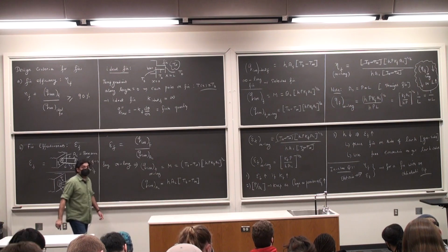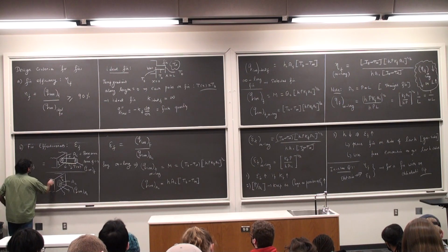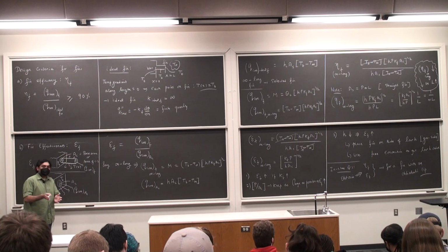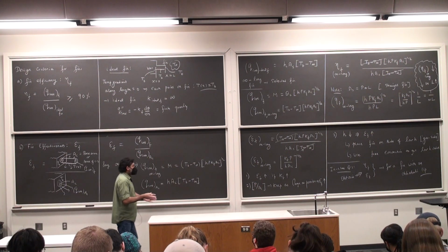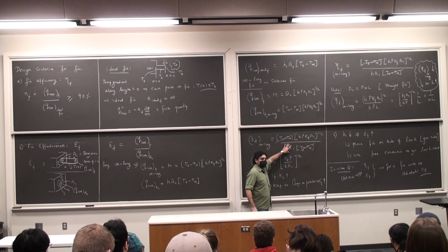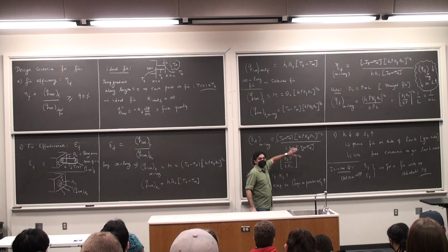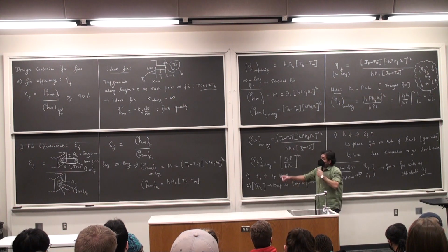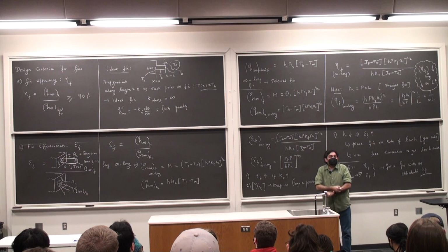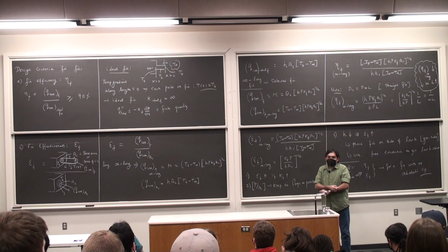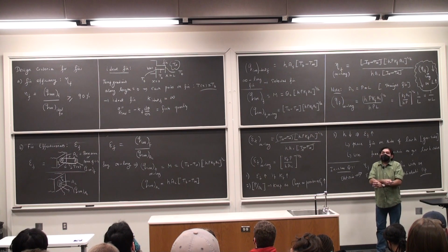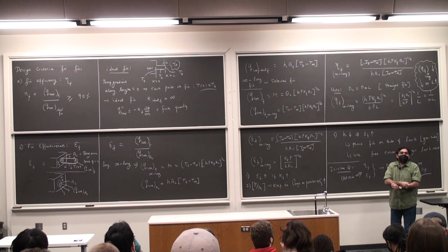Things that do not change: the denominator in the efficiency and effectiveness does not change whichever fin you select. So that's going to be the exact same denominator for the effectiveness for any kind of fin that you select. The other thing, if I look at efficiency considerations, I have an ideal fin. Once again, the denominator there does not change. The only thing that changes is the numerator in both situations. It's a small tweak from an infinitely long fin.